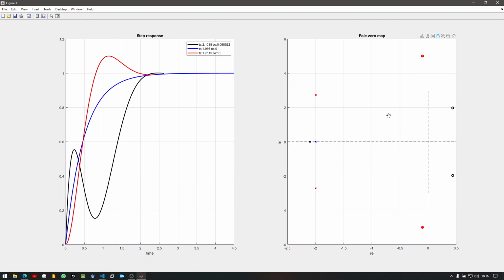So this determines the zeta and omega values, and then those values correspond to the settling time and overshoot values that are given here. Keep in mind that the second order approximations work for a range of zeta values, and there are approximations, so there could be some errors as you can see here. But this control structure looks like it is working as expected.